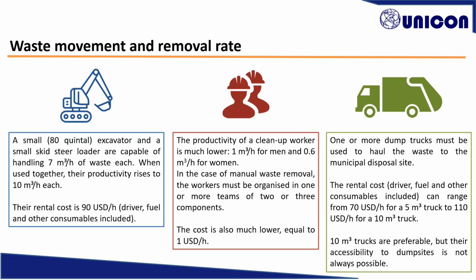For the removal of the dump site, 1 or more dump trucks must be used to haul the waste to the municipal disposal site. The rental cost can range from $17 per hour for a 5 cubic meter truck to $110 per hour for a 10 cubic meter truck.